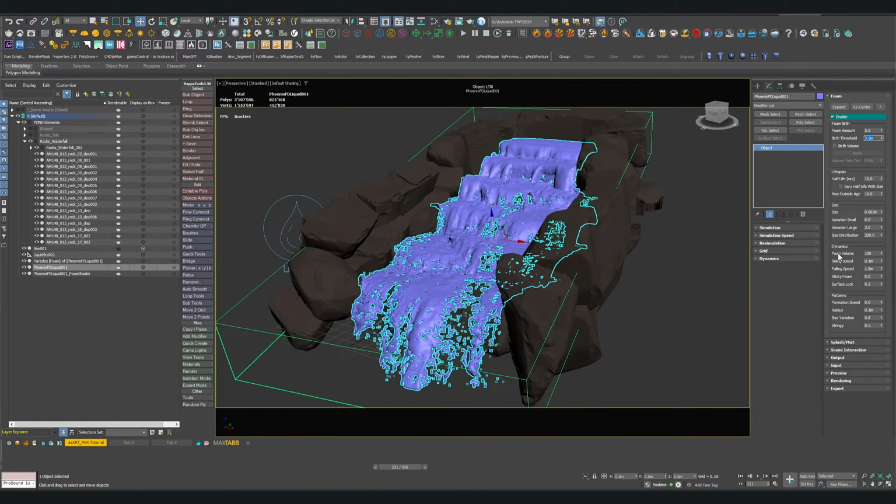So we don't need, for example, the foam volume because we are not creating a beer simulation or something like that. And then the rising and falling speed, these are actually okay the way they are by the default settings. Then formation speed and so on, we can change it later on. We don't need that formation speed actually for this simulation.